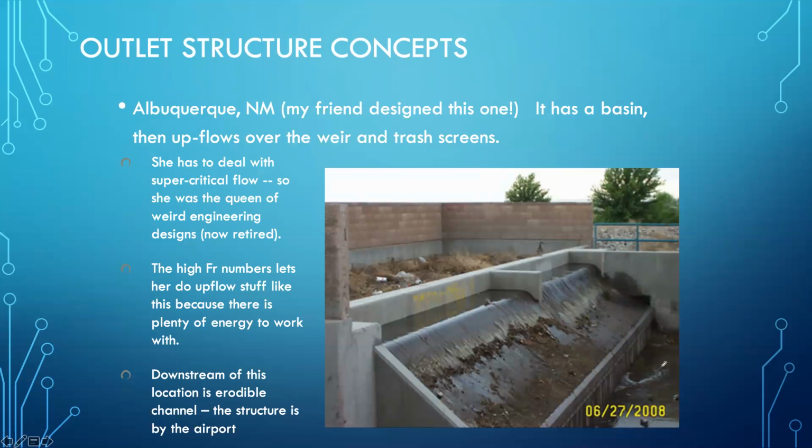The flow comes into this device. The photograph doesn't capture the whole thing. There's a stream that diverts flow into it. It actually comes underneath all the stuff that we're seeing, goes into this grit chamber, which captures all the floatables and large objects.